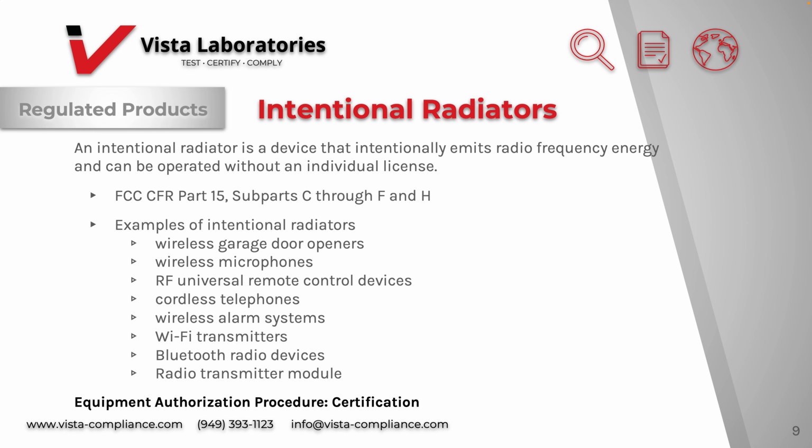An intentional radiator is a device that intentionally generates and emits radio frequency energy by radiation or induction that may be operated without an individual license. Intentional radiators are regulated under FCC Rules 47 CFR Part 15 Subpart C through F and H. And again, this is where you can find the criteria or threshold limits for a product to pass evaluation measurements.